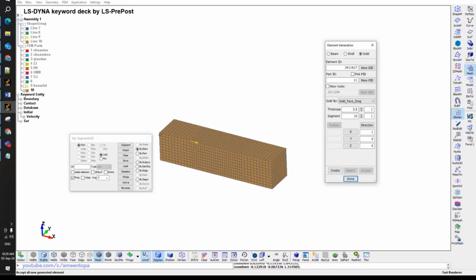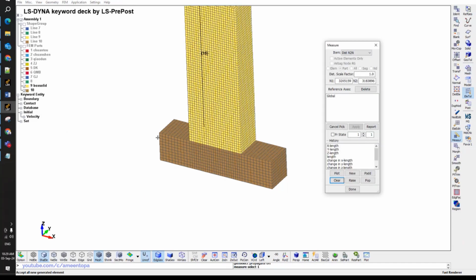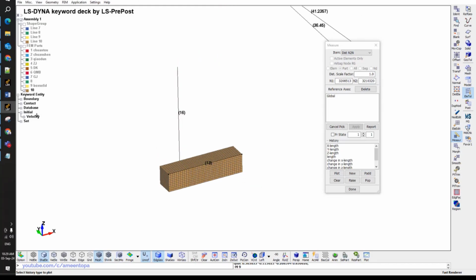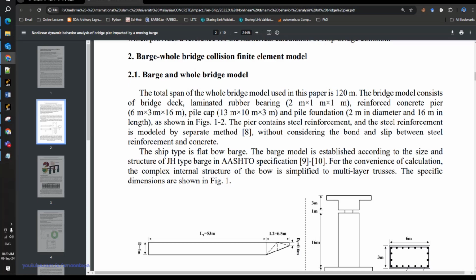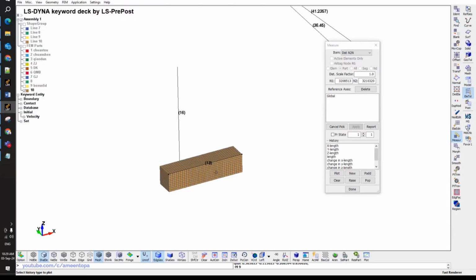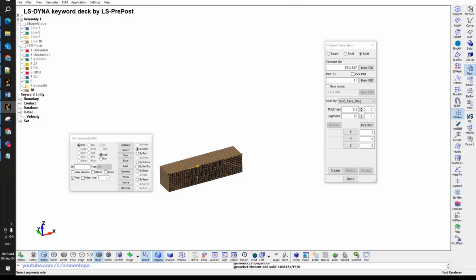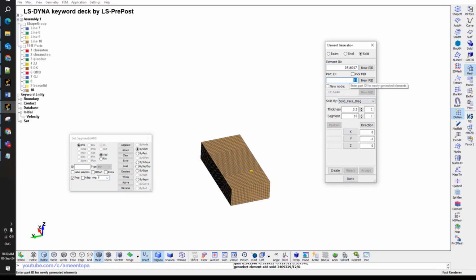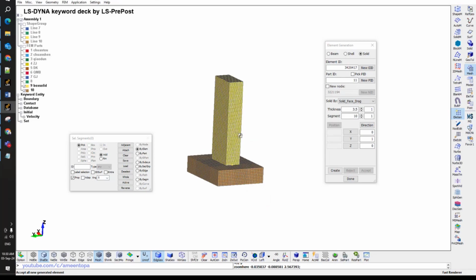Now you can see from the side view, this one is okay. The length is 13 meters. You get the idea of where I'm going. Now we do the same thing for the width. Here it is 3, and I want to make it 10, so I have to add 7. Again 3.5, 3.5. I drag in the negative y with part ID number 10, and here also part ID number 10 and drag in the positive y. Now we are done with this one.